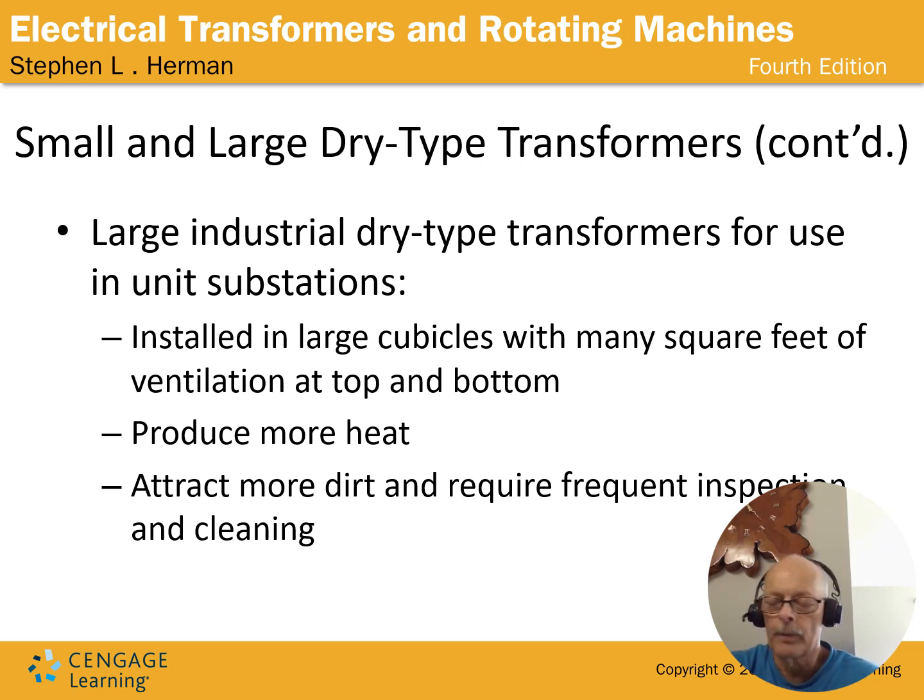In a lot of places I have been, there are air filters mounted on these enclosures, and there's a preventive maintenance procedure. You go by, change out the air filter, observe the transformer itself, make sure it's still clean, and go on your way. The air filter keeps them from getting dirty and not conducting heat very well.